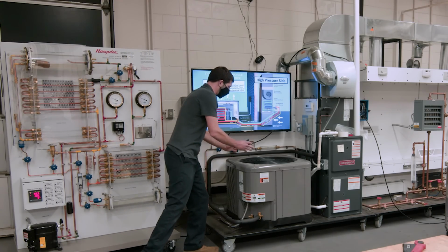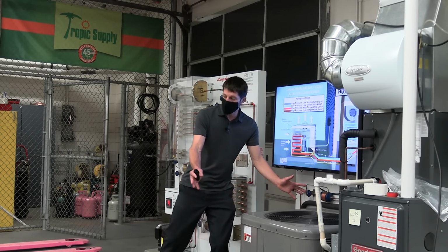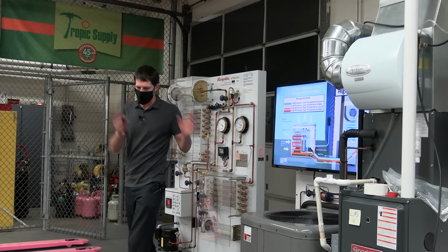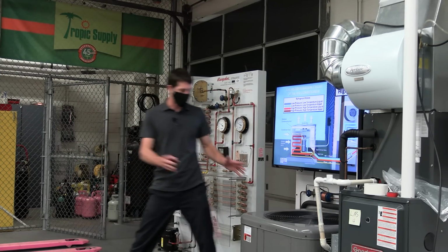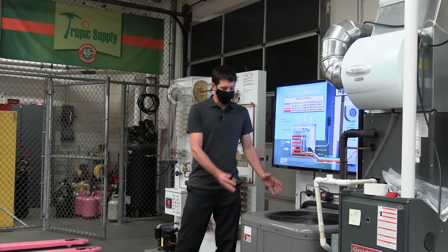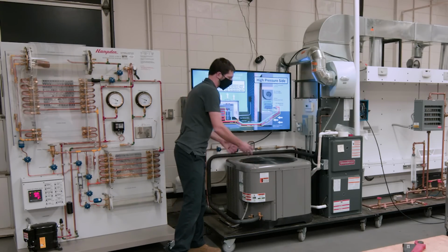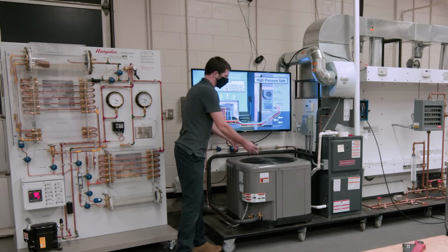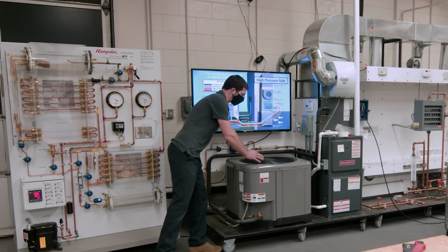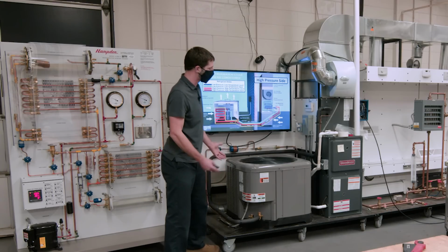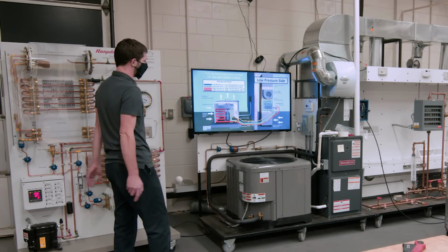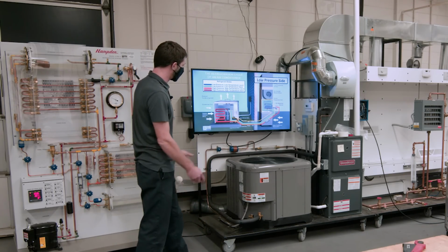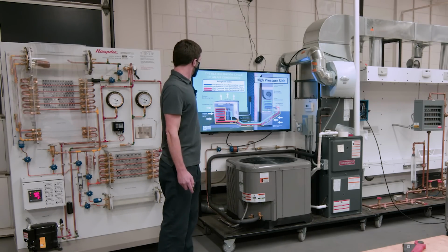There's ways that you can fool the outdoor unit. There's no logic in reference to this computer board wise on the standard systems, but you can fool the outdoor unit into thinking it's a higher temperature than what it actually is by putting a charging jacket or putting a piece of plywood across here to block the airflow, and then try to get the saturated temperature up to a higher temperature. Let's just go to the basics here.